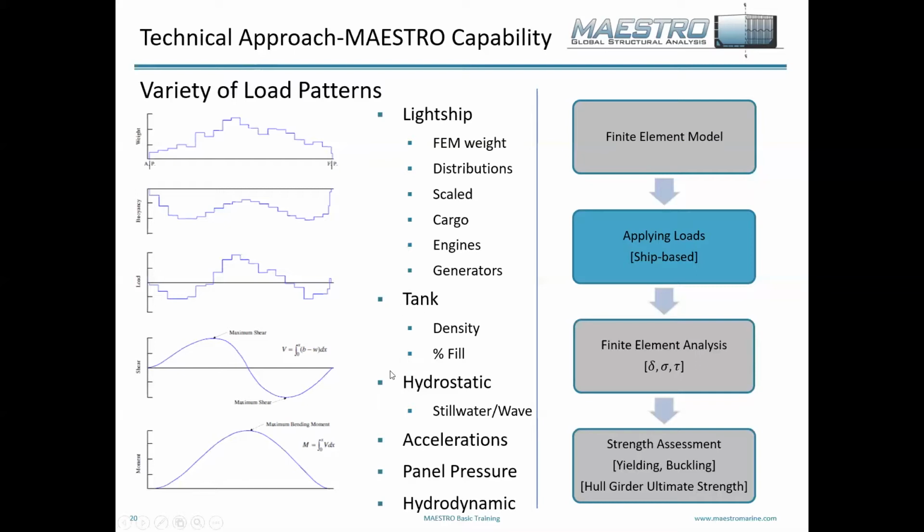For the hydrostatic loads, you can use either the still water condition or apply a wave of some sort. Now that wave can be user defined, a simple sine wave or trochoidal wave, or it could be the effects from the output of Maestro Wave. But that'll more create a load pattern, a pressure pattern on the hull and accelerations and so on, as opposed to the traditional hydrostatic wave.